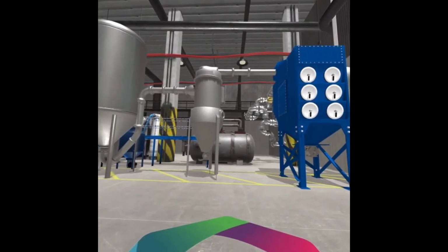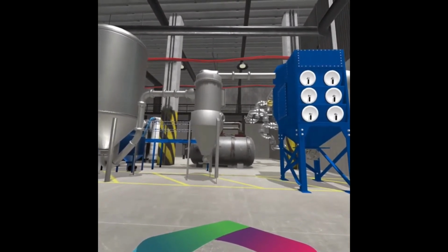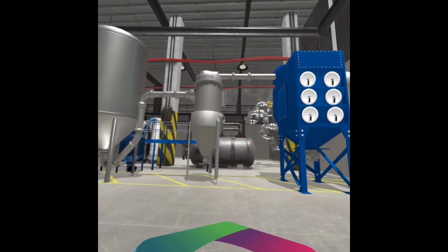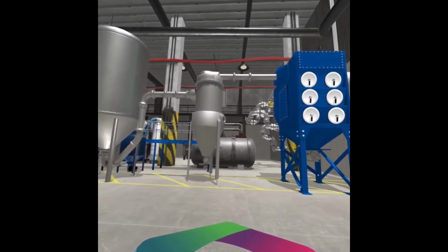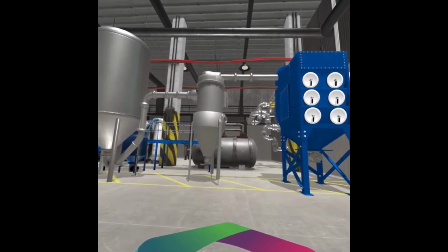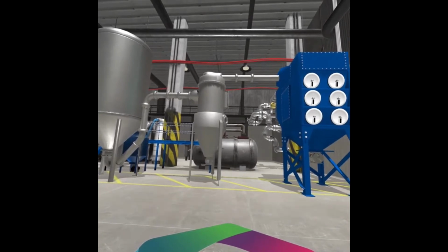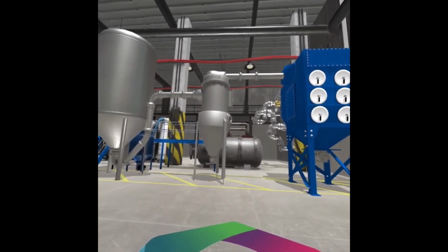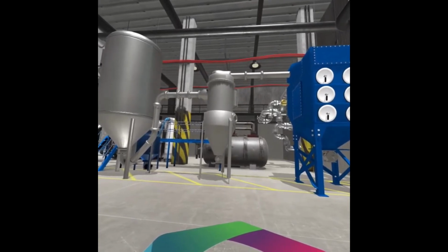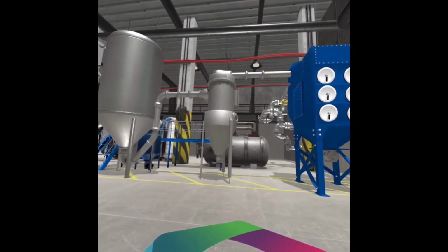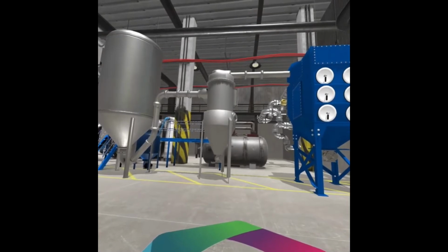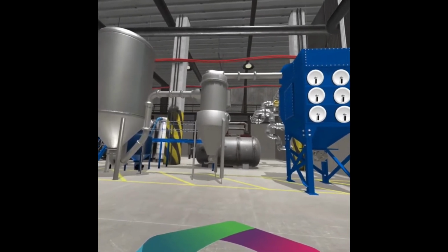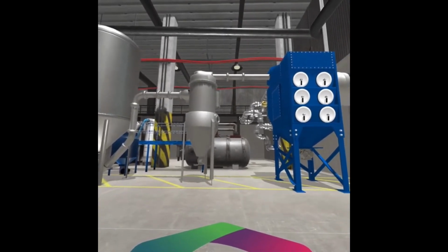Let's take a closer look at the pressure levels in the dust collector as the explosion occurred. With this event, we saw a rapid pressure increase occur in less than 100 milliseconds. That's 3 times faster than the blink of an eye. When the pressure reaches the maximum level, the process vessel is unable to contain the explosion. But what if the pressure could be held below the vessel's limits?